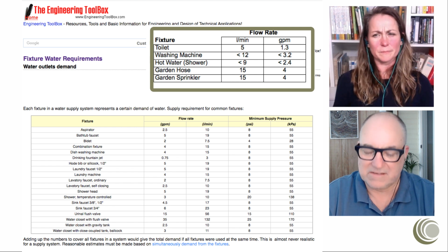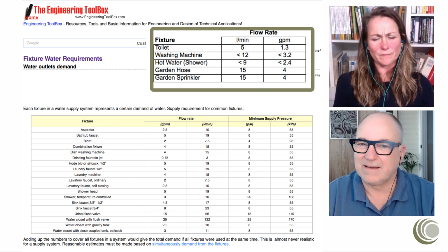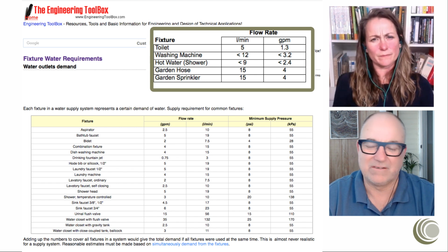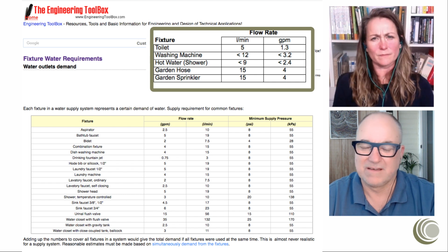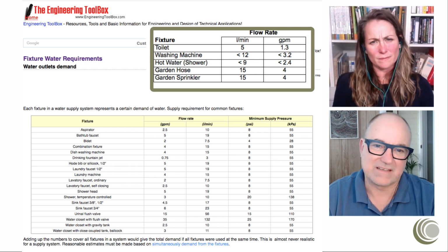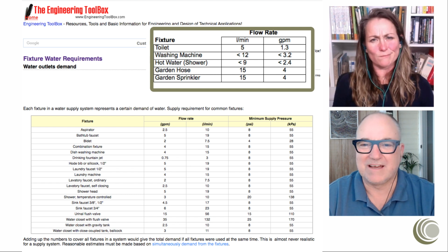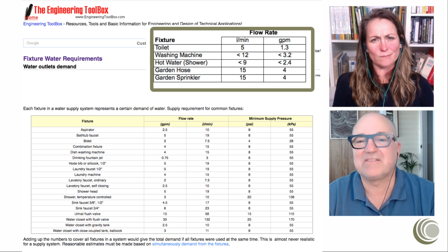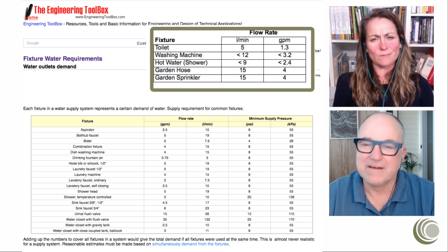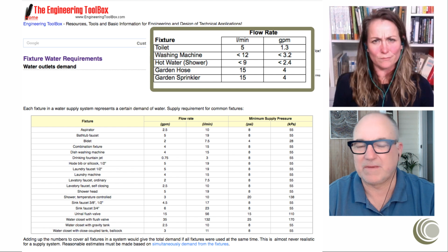And we immediately noticed that we have a more even and higher pressure flow rate, and the pumps worked far less hard, is that the right way to put it? The pumps used a lot less energy, and you could tell they were not working as hard now that the supply lines were short and there were not many bends.